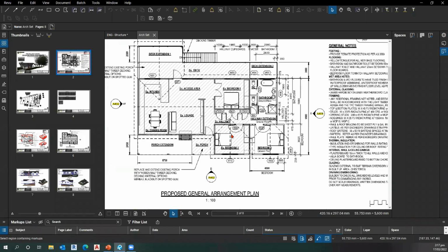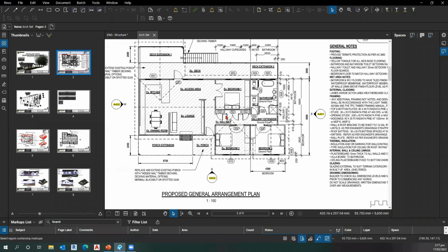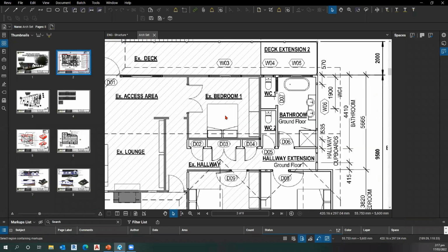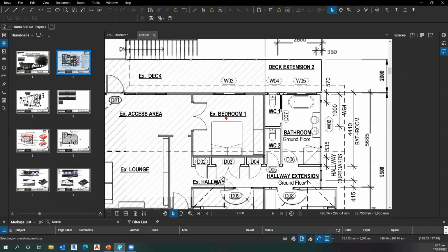Okay, now let's look at bedroom 1. Let's use that as our first example. I'm going to click on this little floor plan with a plus icon. If I hover over it, it says add space. I'm going to click on that. And you see Bluebeam is helping me out by helping snap to the walls. I'm going to click and hold, create my square.